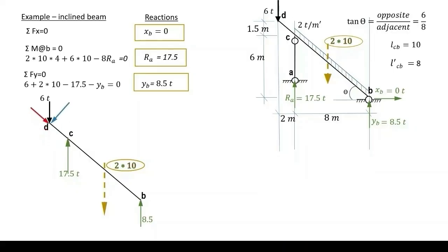Each force is analyzed into a red component to draw the normal force and a blue component to draw the shear force. The distributed load is drawn in a dashed line to remember all through the solution that it is distributed and not concentrated.